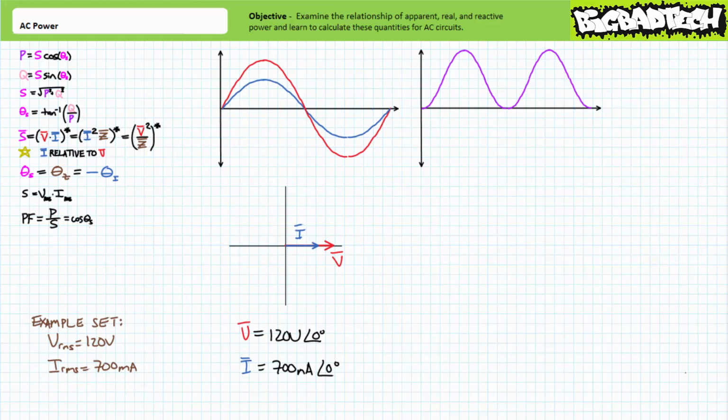You should observe a recognizable pattern as we walk through this set. Additionally, you should anticipate our calculated results to correlate with our previous general expectations regarding how the degree of phase shift between voltage and current allots apparent power into real and reactive portions. Our first plot shows voltage and current to be perfectly in phase with one another. Our previous thought experiment led us to believe that there will be no cyclical exchange of negative and positive power. As such, reactive power Q should be equal to 0 VARs.